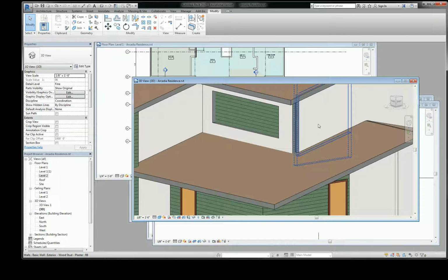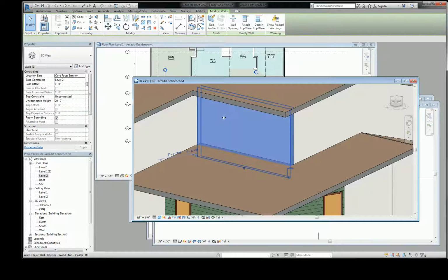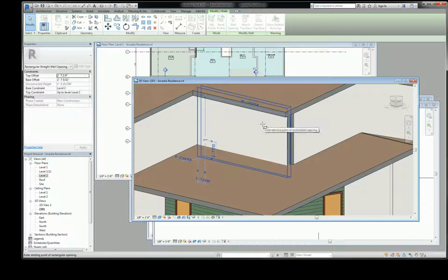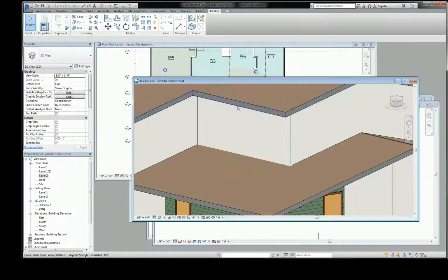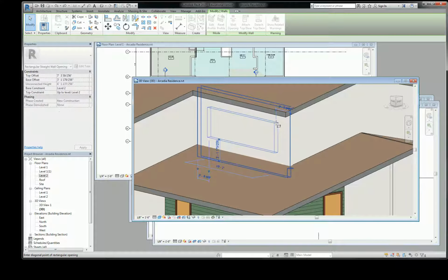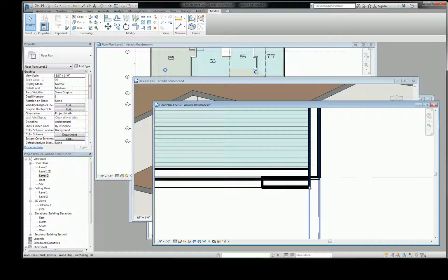Right, that's one option. The other option is using a wall opening, which functions pretty much the same way. You just need to click the wall, click on wall opening, and then very simply put, I messed that up, hang on. There you go, just click the wall and then draw where you want it to cut. And it looks like it messed up that little corner again.